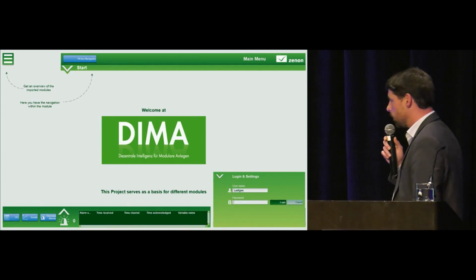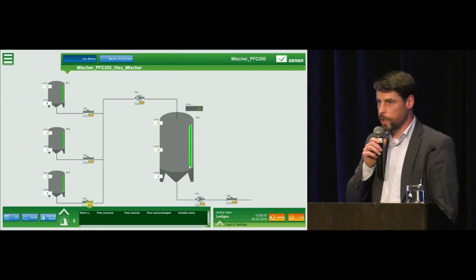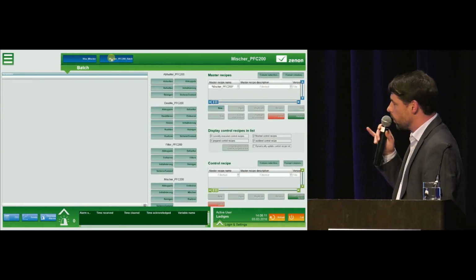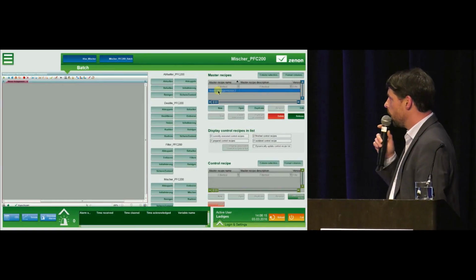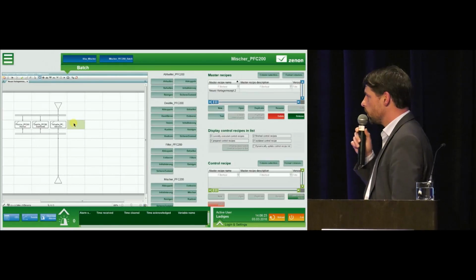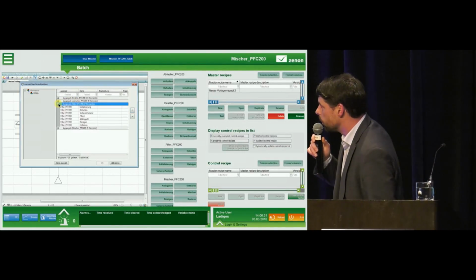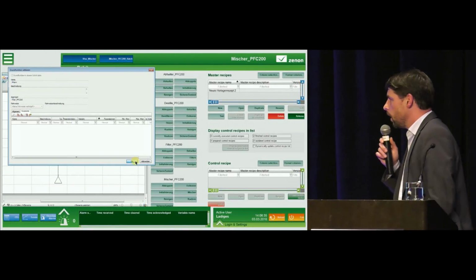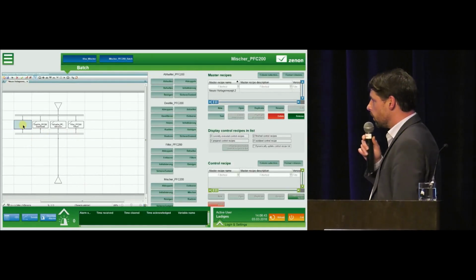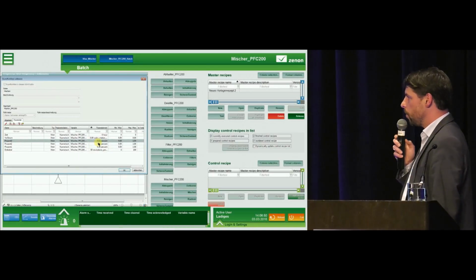There it is. First check in the runtime, and these are automatically generated HMI pictures, totally come out of the MTP specification. Nothing manual inside. Also the sensors and actuators are on, and the batch system can be added now with the phase of the needed service. Here's a list of services which are read in. There's the filter, and the service is filtering. And now it's put in the recipe, and there's also the opportunity to add or model different parameters.